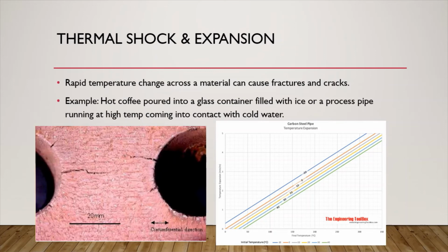Thermal shock works the same way, but is reserved for cases when a material changes temperatures drastically in a short amount of time. Think about putting ice cubes in a glass container and then pouring hot coffee in there. The sudden contraction and expansion from the temperature change produces a large amount of stress and strain on the glass, and it will shatter it if these forces are large enough. The same applies for materials used in piping.